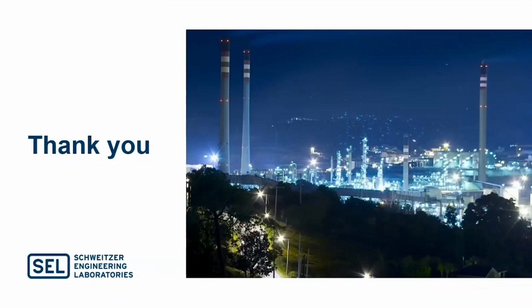Hi, Tristan. I can take that. It's Ramesh. As of now, mirrored bits are not going to be able to support analogs, but there are some methods that you can use to send analog quantities through mirrored bits. However, what we recommend nowadays is to use Ethernet-based high-speed protocols such as IEC 61850 GOOSE that has both digital signals and analog signals capability to transfer that data over high speeds.